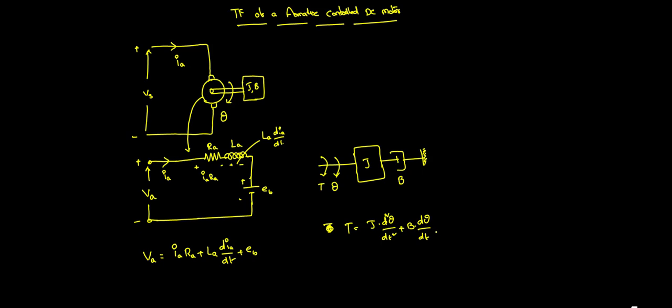Okay, and so this is very important, and up to this is fine. So you found the mechanical system of the motor, you found the Kirchhoff voltage law, and now we have to bring these two into a common platform. What is that common platform? It is the torque, because the common thing between the electrical and the mechanical is torque. So the torque